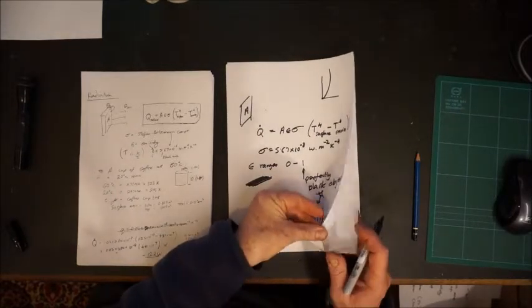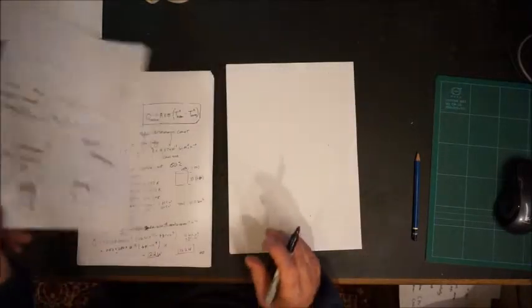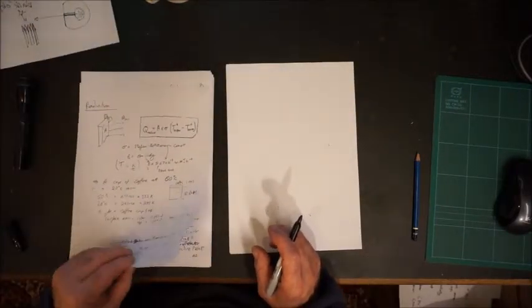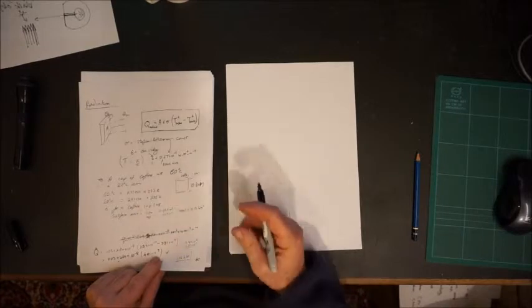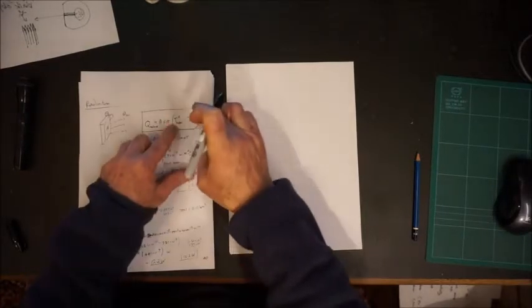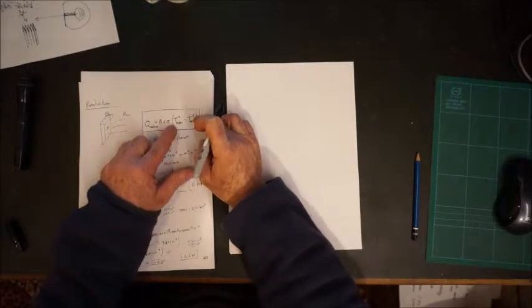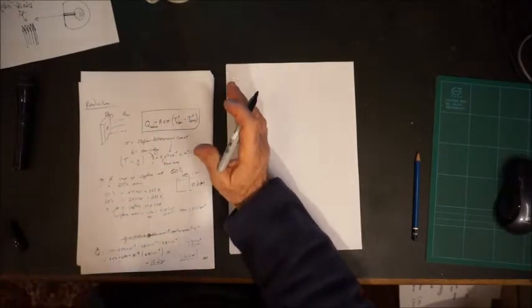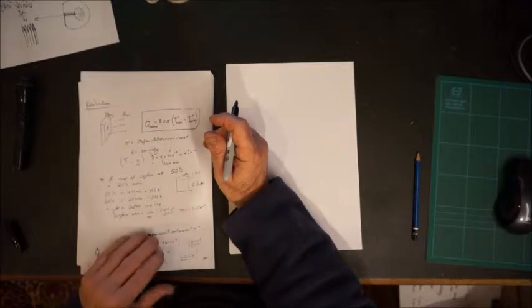Okay, so that's radiation. There's some examples here. Work your way through them. They're simple math. Always remember it's T to the 4 of the surface minus T to the 4 of the environment. It's not just the difference between the two. That does not give you the right answers.